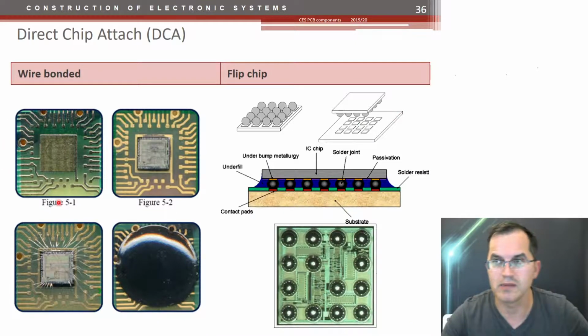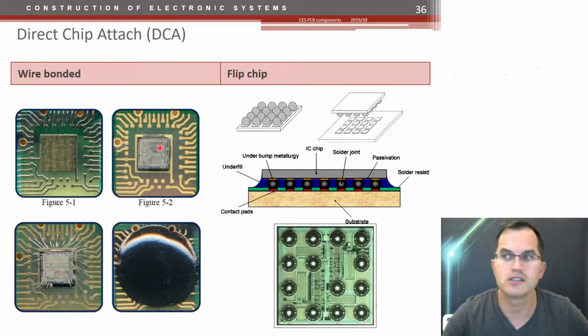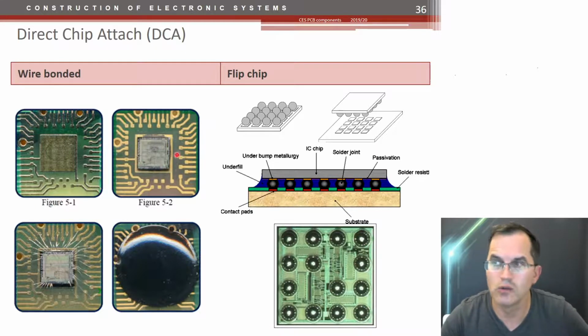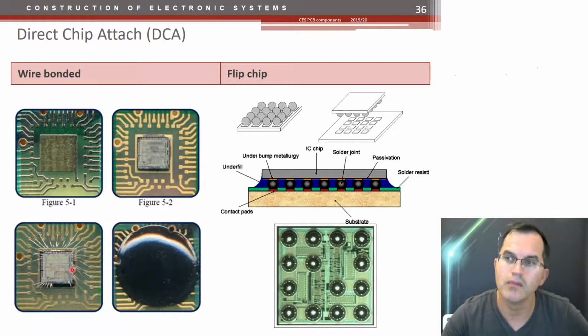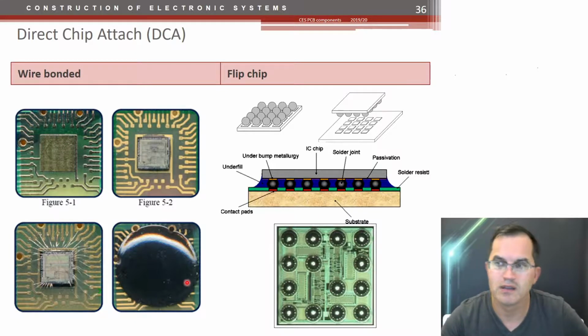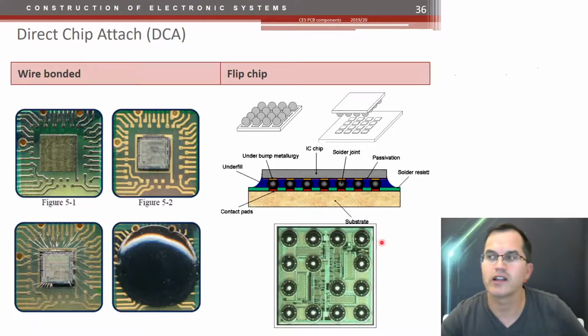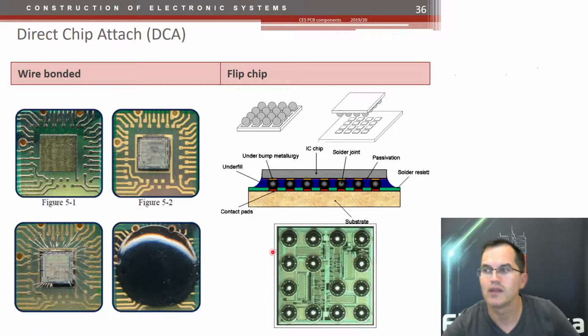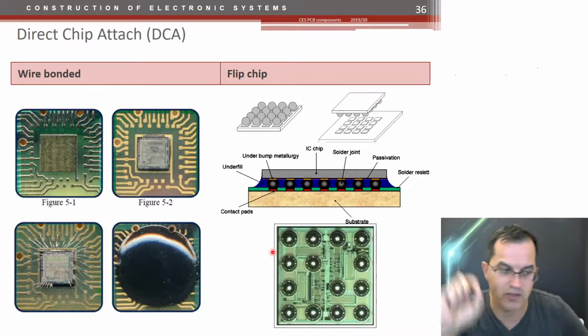So this is our PCB, and we directly solder or glue the chip on that area, bond it, and then fill it with some epoxy sealant and protect it from the air. The flip chip technology flips the chip around, does not use any bonding wires, and you solder it directly on the PCB and protect it, or even not. You can see a bare chip die on, let's say, a Raspberry Pi, for example. You see small bare chips there.